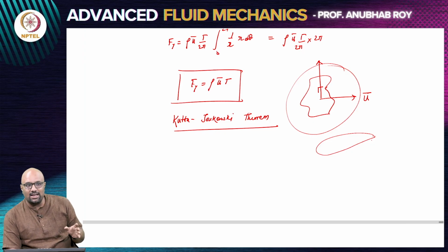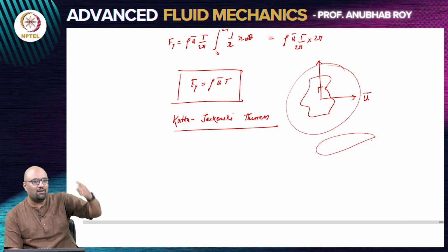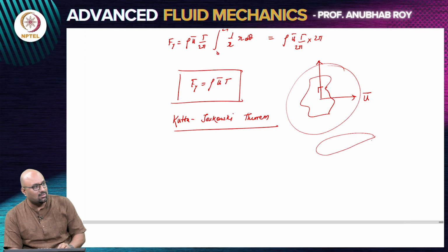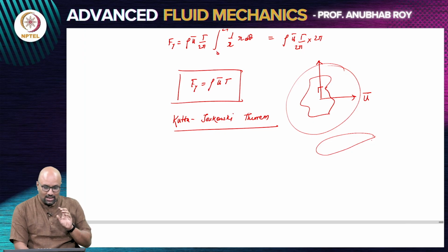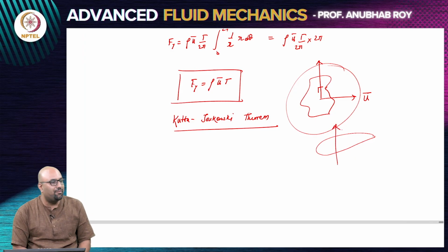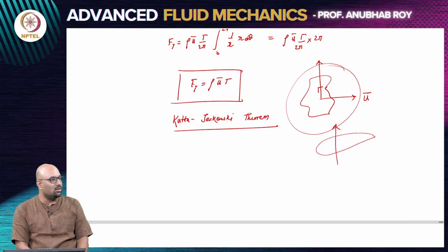I am not trying to say that viscosity is not important here, because the next lecture we are exactly going to hit the nail on the head by asking where did the circulation come from. We do not have an airfoil rotating, right? There is no spin or anything that is there. So, where is the circulation coming from? That is obviously not addressed yet, but the powerful point that it says is that if there is a circulation that is there in the problem and there is a uniform translation of this object, you are going to get a lift, which is a force normal to the motion.